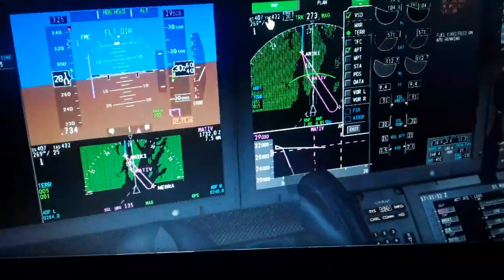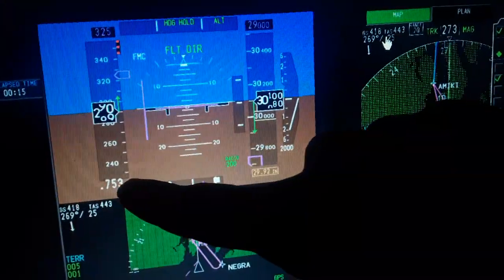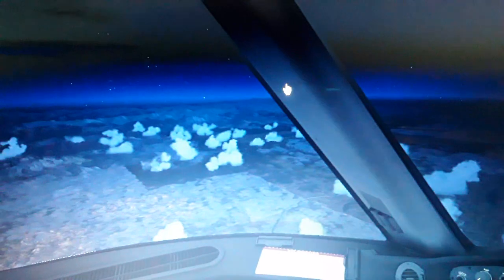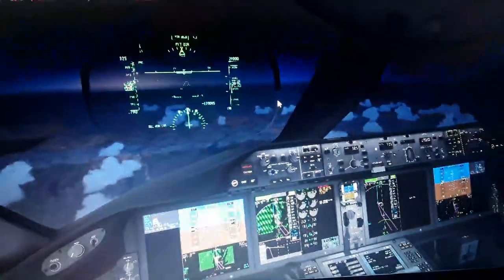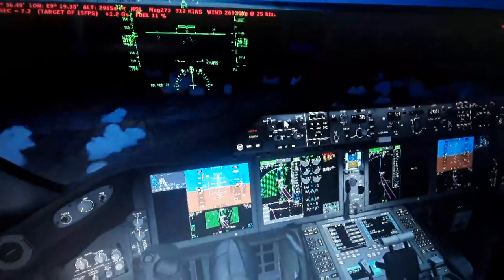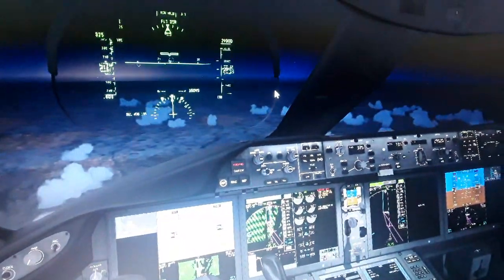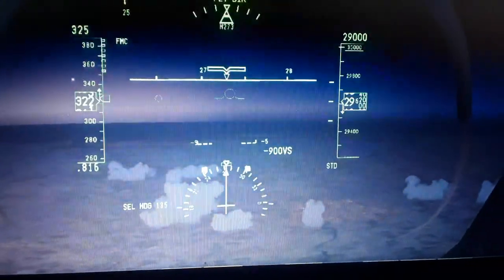We keep flying manually. We can also connect. So this is the airspeed limit now, Mach 0.75 or about 900 kilometers an hour. Gonna be flying through 29,000 feet here. So we have a higher Mach speed. We need also to pitch down a little bit.